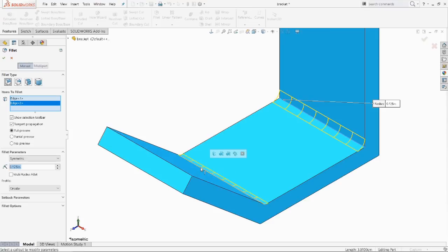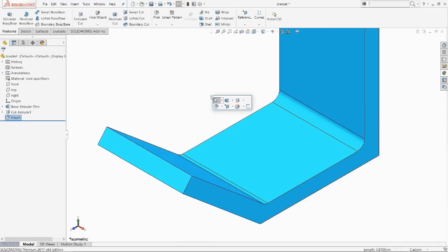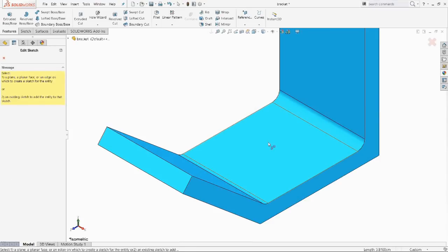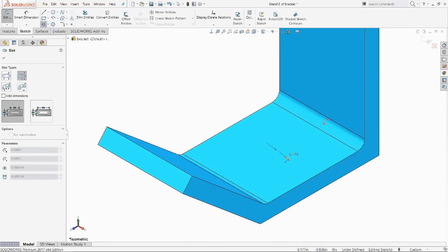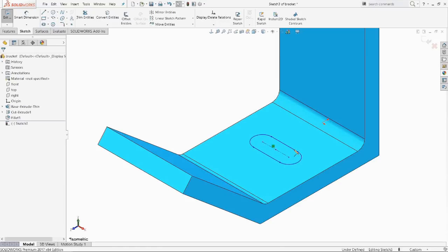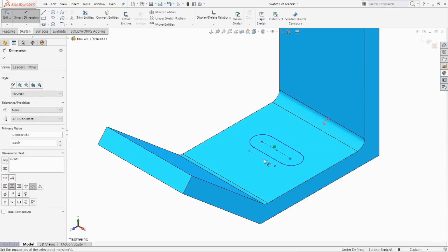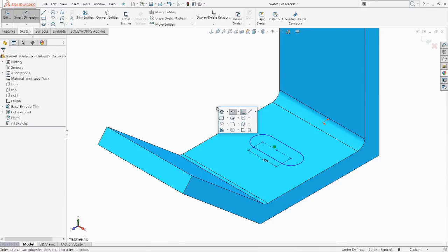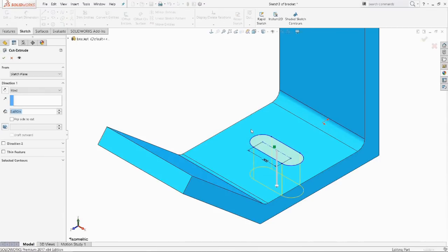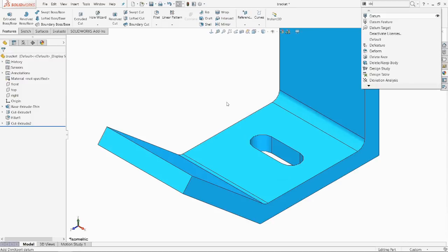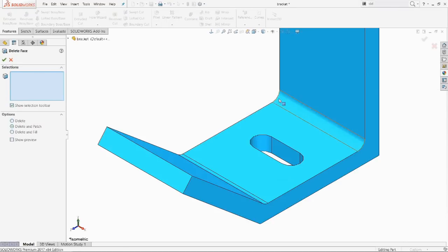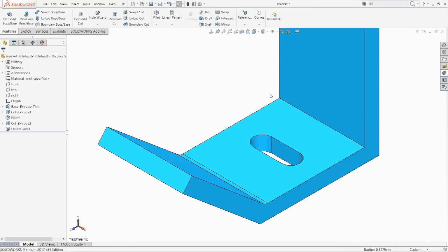I want to add a fillet, so I hit S and grab the fillet tool. Now I hit S, I want to start a new sketch. And I hit S, and now it's the sketch features, or the sketch options for that. I hit S again. All I'm doing is hitting S, and that bar is popping up right next to where my mouse is. So I'm doing a few things. I'm minimizing my mouse mileage. I'm not going all over the screen. And I'm getting these tools right at my fingertips. Right? So it's more efficient, easier, quicker, doing all sorts of stuff here with that S key.